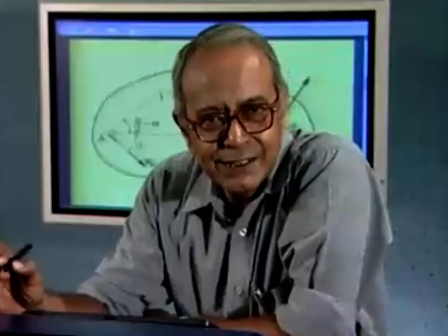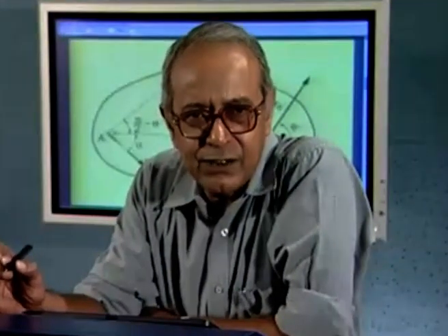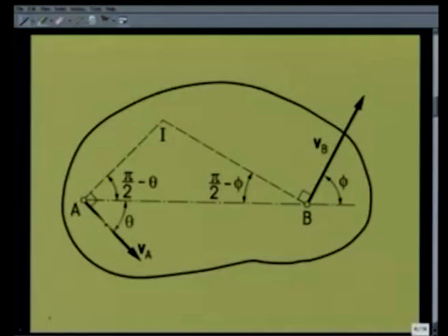To prove the existence of the instantaneous center of velocity for a rigid body under plane motion, let us consider this figure. We consider 2 points, namely A and B, whose velocities are given by Vb and Va. We have already seen that if Va is given and omega is given, then Vb is completely determined. That means both Vb and Va, having 4 components, cannot be independent.